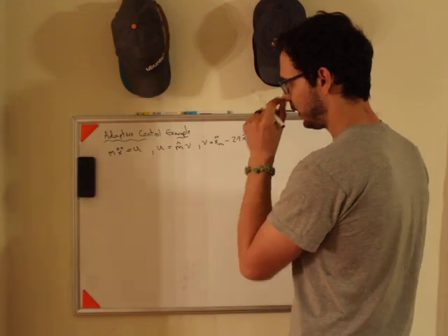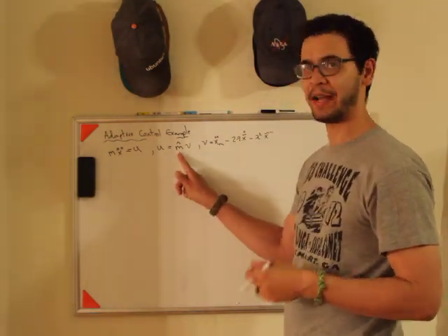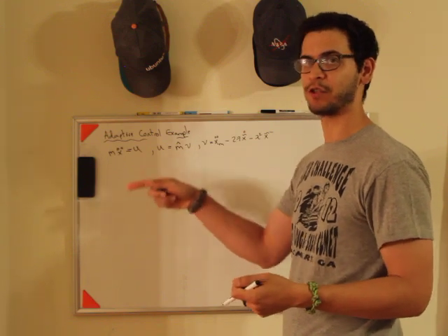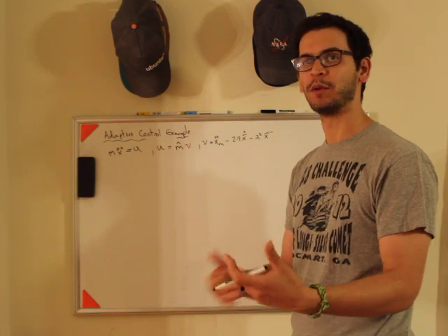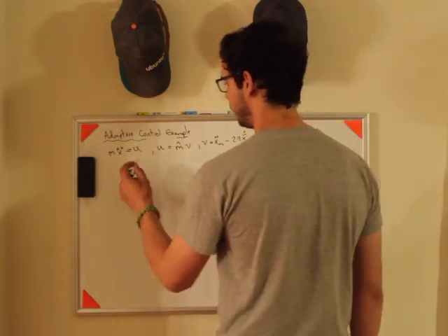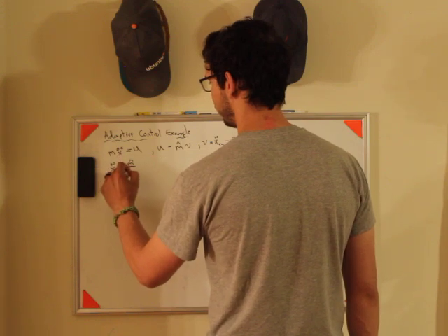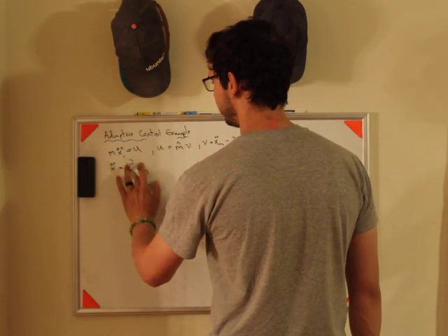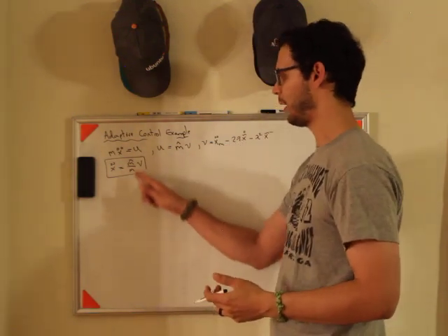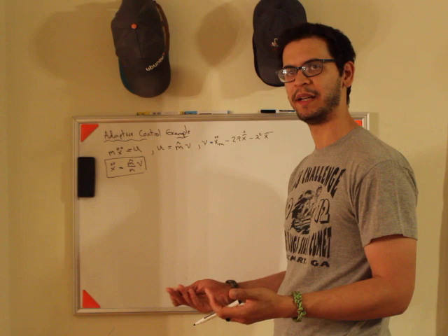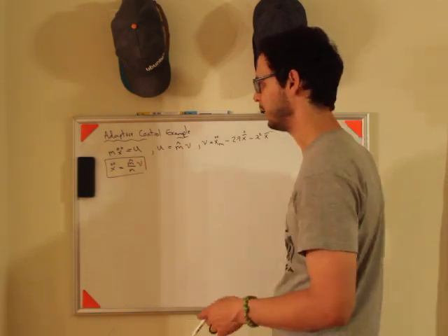Okay? And again, if my system was robust enough, if I had a good estimate for m hat, I could just throw this controller on there and it wouldn't work perfectly, but it would work okay. If you look at this, this would be x double dot equals m hat over m times v. And so this isn't exactly perfect, the m hat doesn't perfectly cancel, but if m hat over m is close enough to 1, everything would be fine, okay?